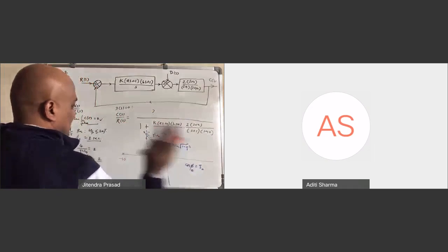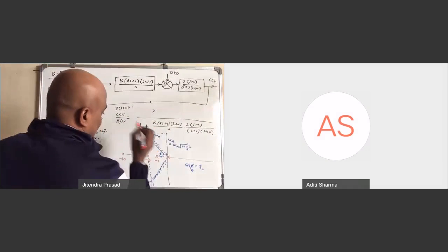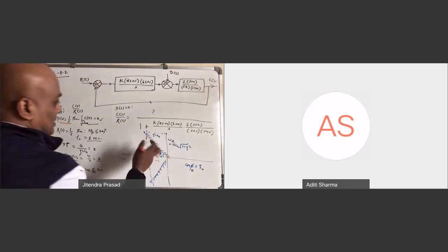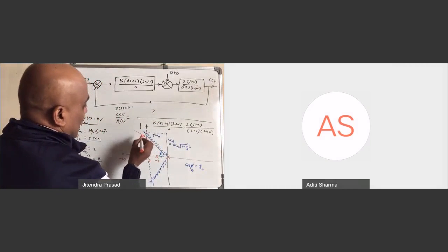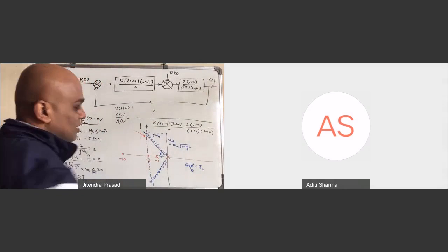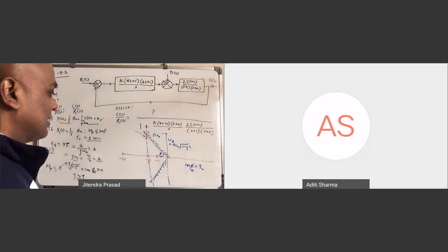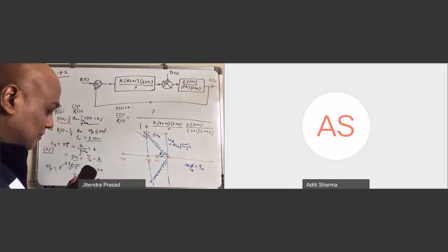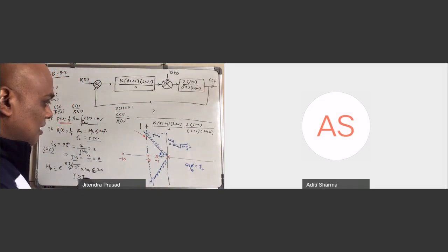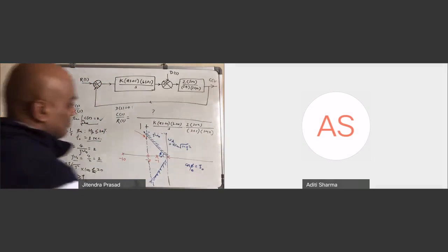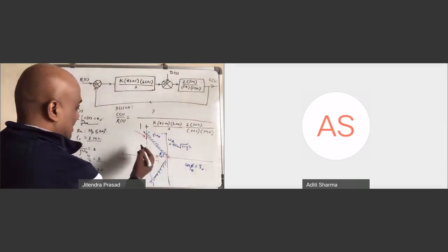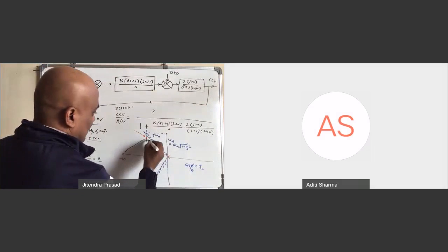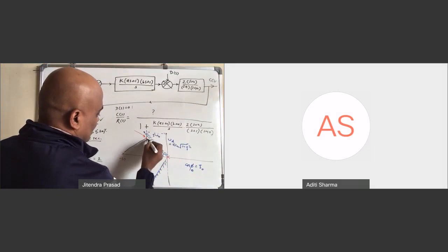Regardless of that, let us say you have chosen this point. Then you want the root locus to pass through this point now. That's what you want, right? Okay, so how will you decide? For that we are going to apply the angle rule. You are going to connect this point, this point, this point, and this point.